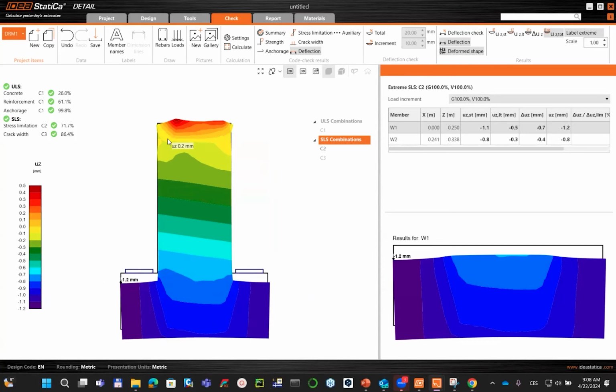Of course, these boundary conditions somehow affect the structure a little bit, but you need to know what your area of interest is. My area of interest is this part. So this is the reason why the results here won't be affected by the constraint, but it's everywhere. It's in every finite element solution. So it behaves really well.